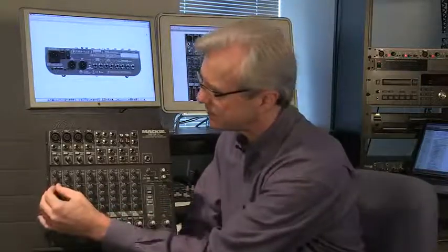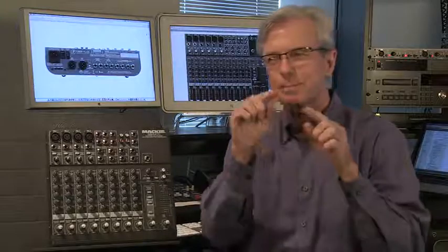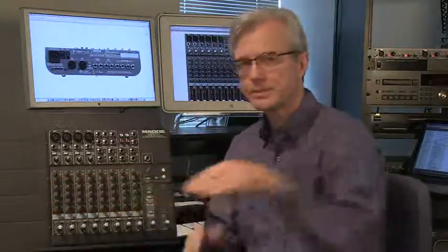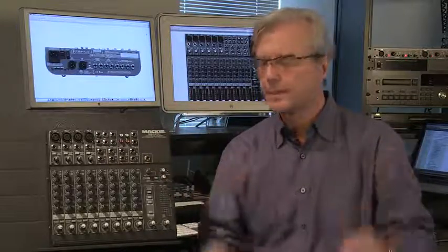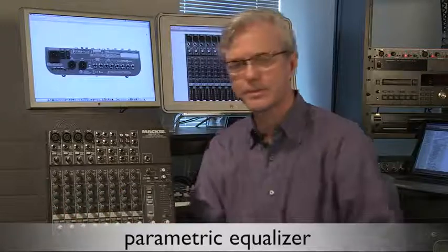And then the upper one on this one is going to be about 12,000 hertz. So I can control 12,000. So when I amplify or attenuate, I'm rolling off 12,000, but really probably up to about 14 or 15,000, and then down to about 8,000 when I move that, because it's a range of frequencies that I'm controlling. Now, this is called a parametric equalizer. This is a simple parametric equalizer.